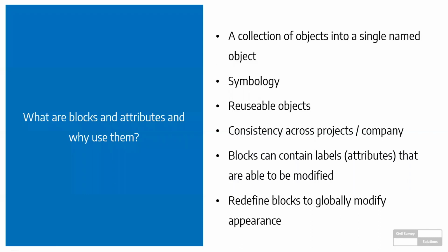Scalable blocks are ideal. You might have a water main and you've got your stop valves and things like that, and you've got different layout scales. You might want that symbol to be the same size in your layouts, so you can make the block annotative, so it scales up and down depending upon your drawing scales. And as I lightly covered before, reusable objects.